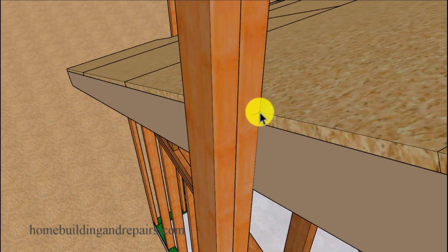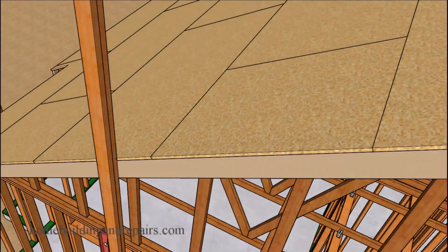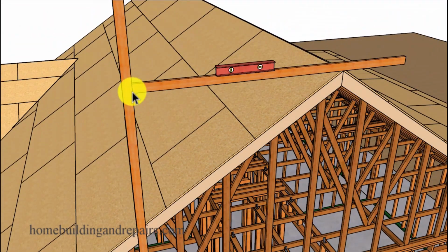And again, we are going to make a mark on the wall framing stud even with the top of the sheathing. And I guess now would be a good time to point out that if you are going to get this as close as you possibly can to the minimum chimney height, then make sure that you take into calculation your roofing materials and anything else that is going to be on top of the roof that could create a problem for this measurement.